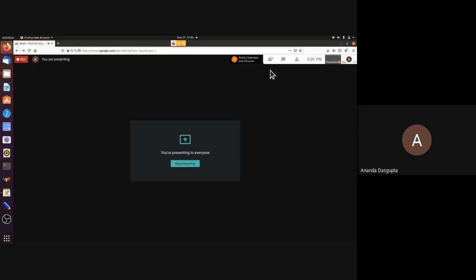However, this is very important. If you have a complicated Boolean expression and you want to see whether it works correctly or not, very often the fastest way to check that would be to have a multiplexer to which you put in the inputs, you see whether the output works. And of course, you combine it with other circuits and see whether you are getting your desired result. So a multiplexer is very, very important for prototyping.